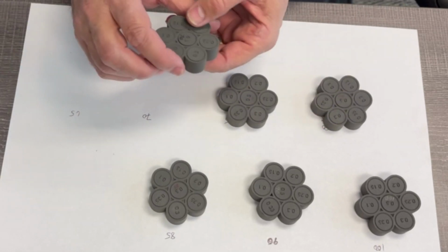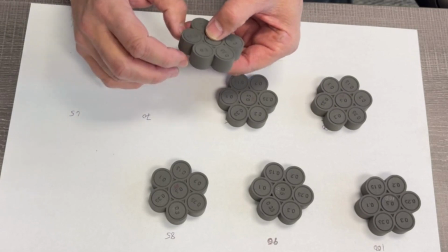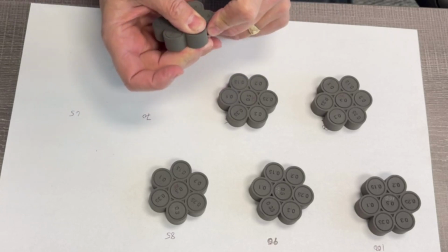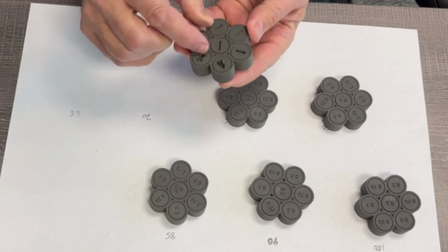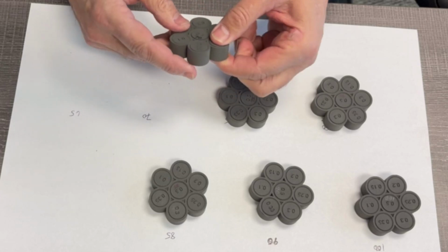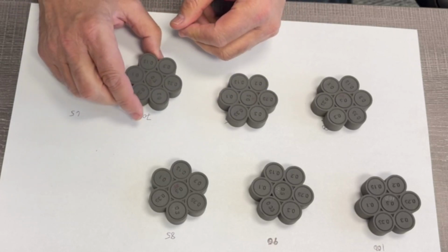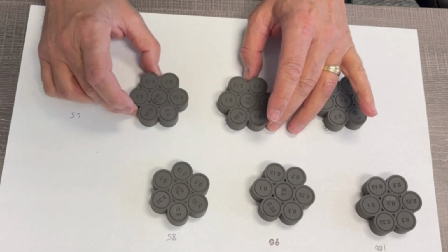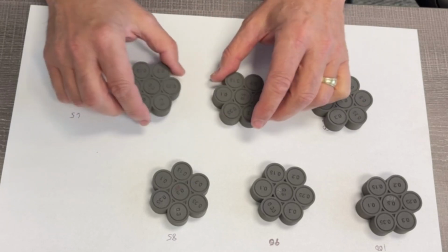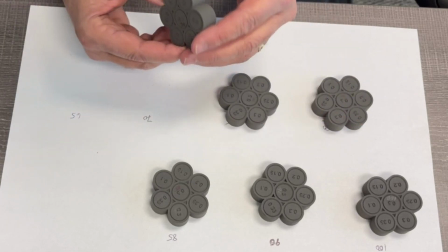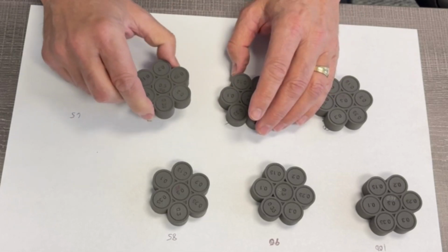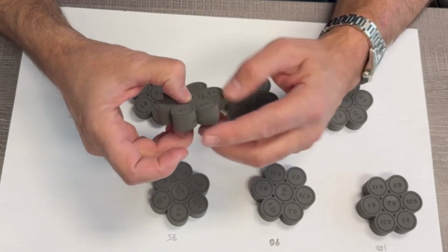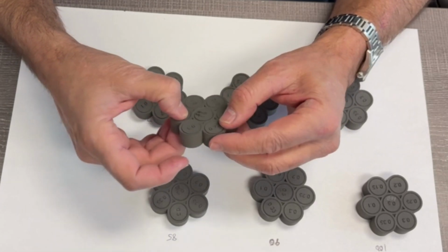So at this point, I feel like we're getting close to where we need to be, but I obviously went to the 0.7 and was part of the group that I printed. I got the 0.35 and the 0.3 to move, once again, it took a little bit of effort. You can see the slot. So there really wasn't a lot of difference. I would say 0.75 seemed to be better actually than 0.7 in terms of getting it to move, but maybe that was just a feel. And once again, the quality of the parts still looks good. They feel sturdy. And then the last one, 0.65, as you'd expect, everything should move up to the 0.3.